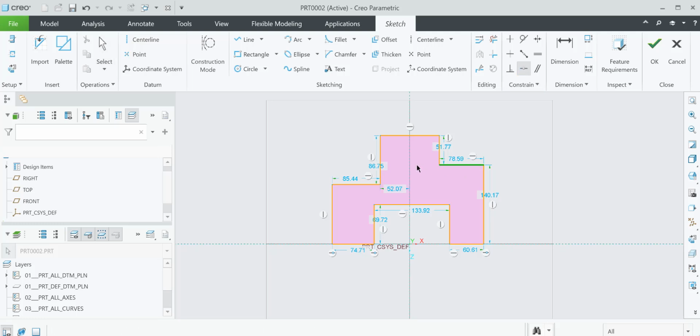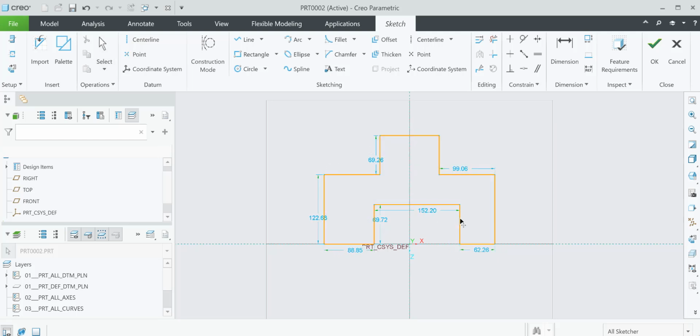Now I'm going to make this line up to this one, the lines. I can use this tool to establish symmetry. Notice I didn't need to have a center line down the geometry. That's pretty helpful in terms of speed modeling. I like to model things so they're not symmetrical, so when I see them become symmetrical, I know I've established the relationship I'm looking to establish.